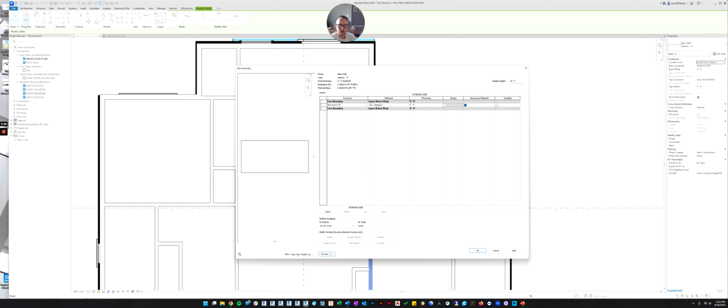It's a layer. There's one layer right here. You can see the core boundary. The core boundary is meant to help distinguish what part of the wall is structural and could be load-bearing, and what part is just finishes. So right now, inside the core for structure, they've just got a generic material called structure.